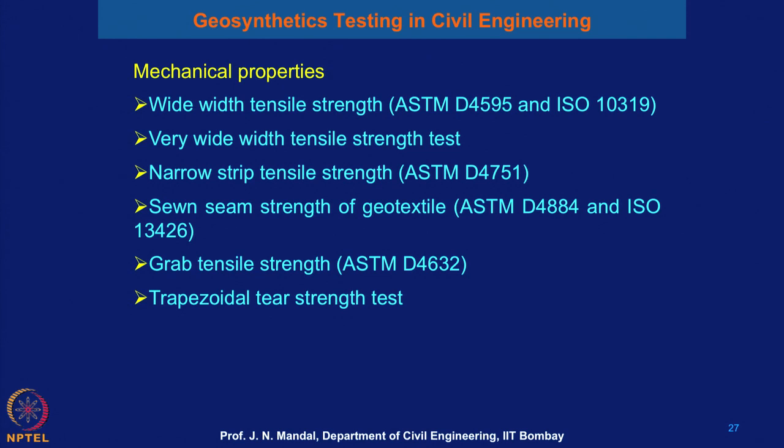You have the very wide width tensile strength test, and the narrow strip tensile strength as per ASTM D4751. So, this should not be adopted for the design and is not recommended. Shear and seam strength of geotextile as per ASTM D4884 and ISO 13426, grab tensile strength ASTM D4632, and the trapezoidal shear strength test.